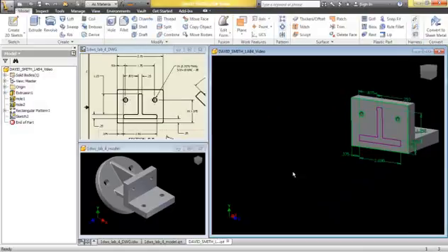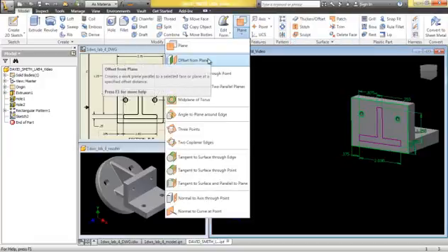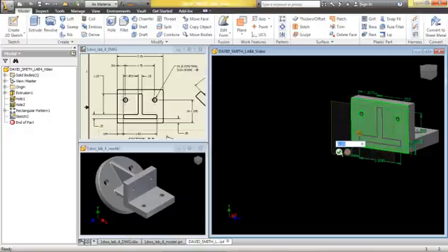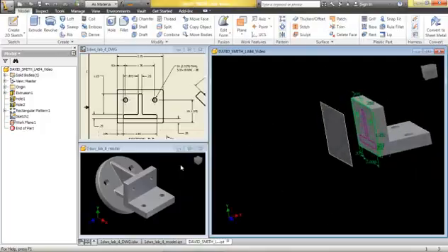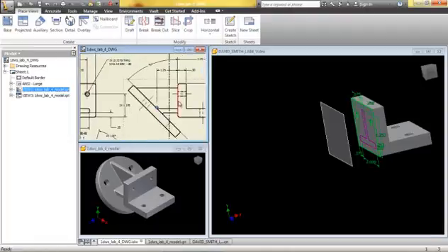And the next thing I'm going to do is go in and create a work plane. I just want to offset a work plane. This work plane here, I want to go out there 1 1/4. So that's out like so. And the reason for that is, if we look at the drawing, it says that from that left edge over to where the T-shape breaks off at 45 degrees is 1 1/4.